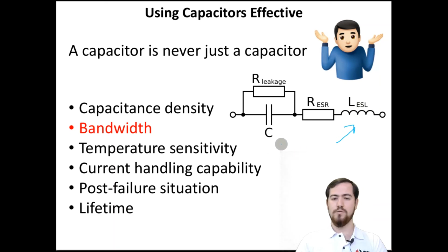Most of the time, we prefer ceramic capacitors because of their wider bandwidth. However, the selection of capacitors depends on many parameters such as the capacitance density, the temperature sensitivity, because the capacitance changes with the temperature, the current handling capability, or the post-failure situation.